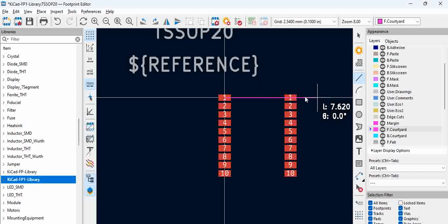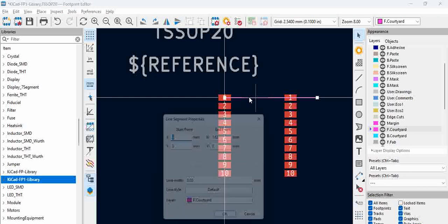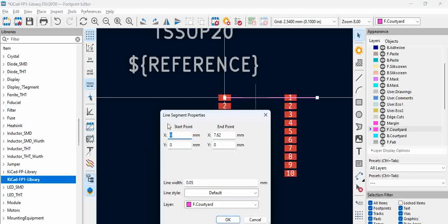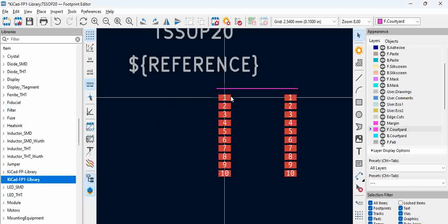Try to draw some line first. Okay, and then the courtyard must be such a way that we have proper dimensions outlined. So we already have the dimensions, and then minus 0.7, 0.7. Let us see. Okay, so the component when placed here comes almost till this point, and this courtyard indicates how much distance it has to be placed.